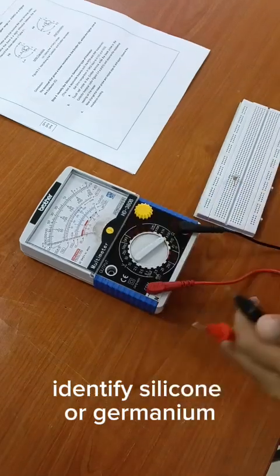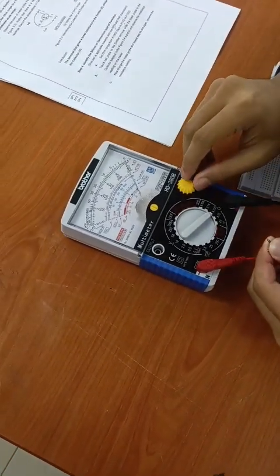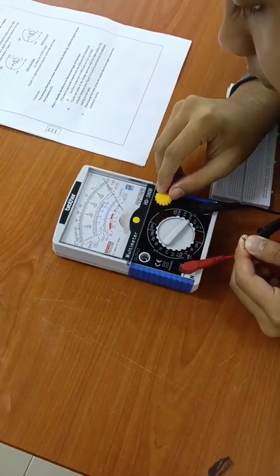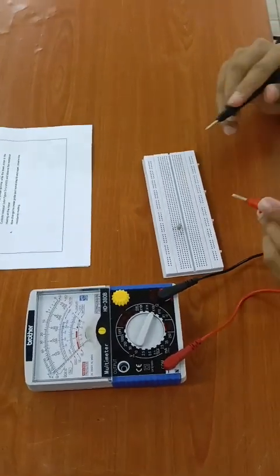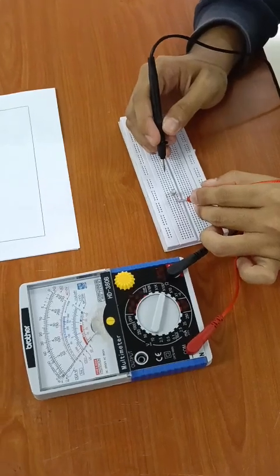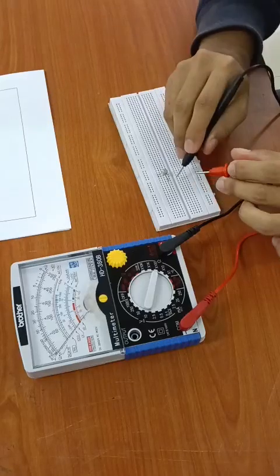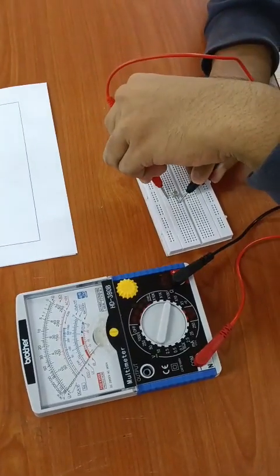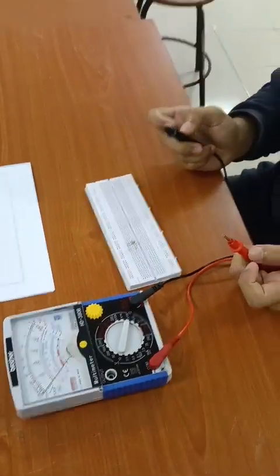Next, identify the silicon or germanium. Okay, we go back to divide by 10, divide by 100, and we do 0 ohm adjustment. Okay, this is how to identify silicon or germanium. Okay, put the 2 probes at another point, not at base. Okay, now we know that it is silicon.